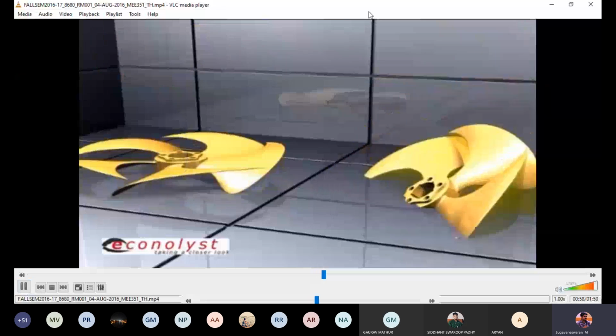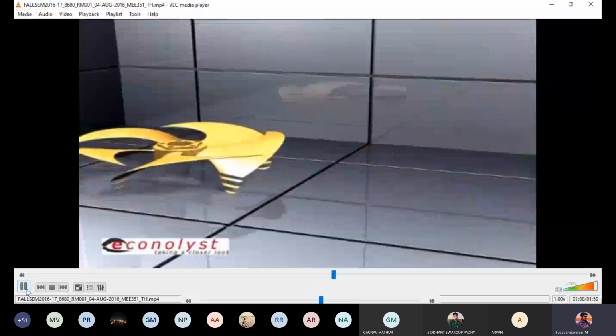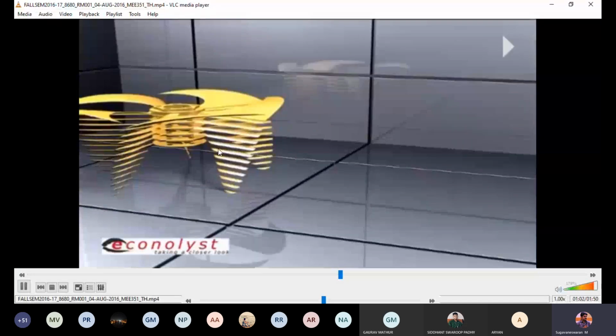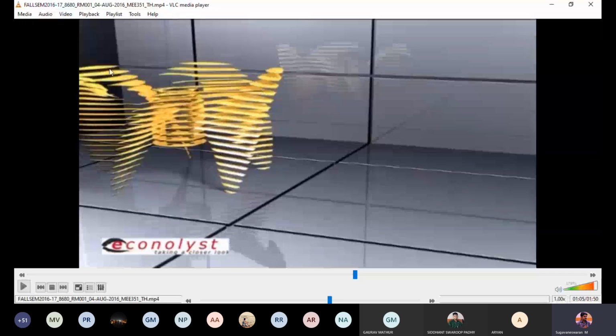That is, the three-dimensional model has to be sliced into thin contours. Each and every contour will have a flat layer. So that is what slicing is. This is how the slicing will happen inside the software, but an exaggerated view is shown here. The three-dimensional geometry is then sliced electronically into two-dimensional layers. Each slice will have a flat face. But when you stack all the slices, you will get a 3D component. That is additive 3D printing.